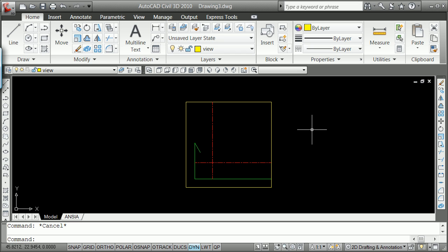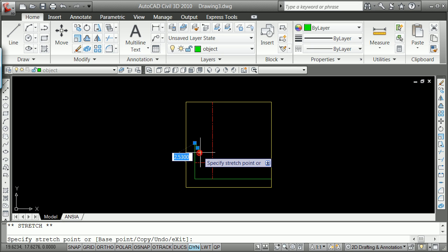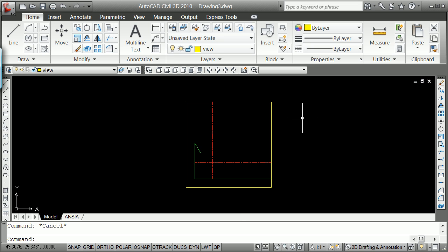So now, once again, what is the way to turn an angle? You have the dynamic on. You left click on the thing you want to turn it about, and then you remember, I don't want the dynamic on, because all those buttons come at you. So you can use the dynamic, but if you turn the dynamic off, you left click over the edge there, and you hit spacebar.